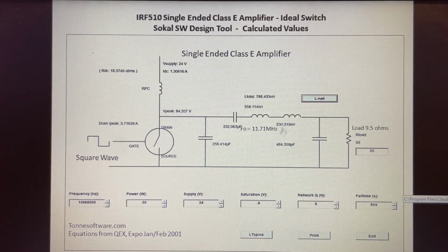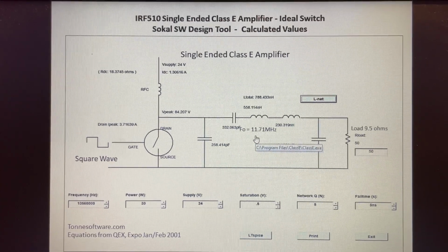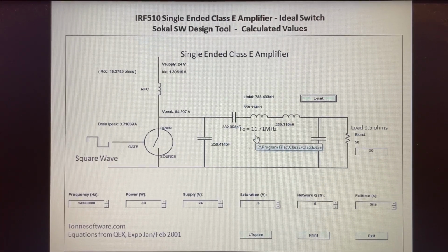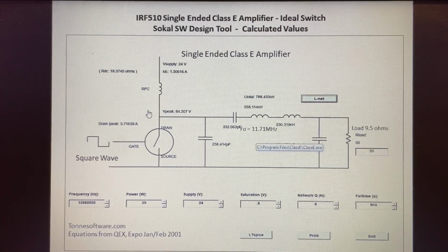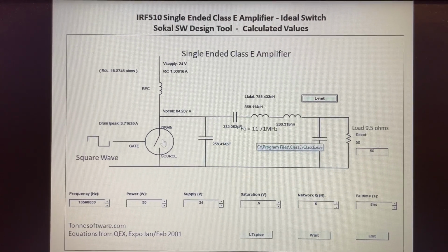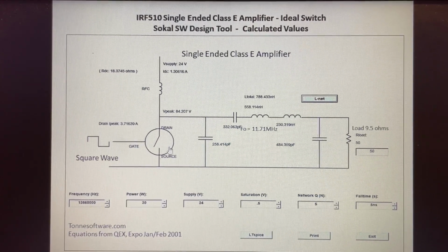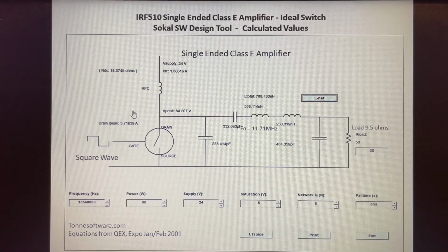I also show the calculation here for the resonator. Okay, the circuit is operating at 13.56 megahertz, but the resonator is actually tuned below that. And there's two impedances to this circuit, not to get too technical, trying to keep the math relatively simple, but there's one impedance when the transistor is closed and on, and another impedance when the transistor is open and off.